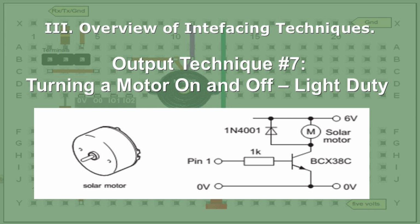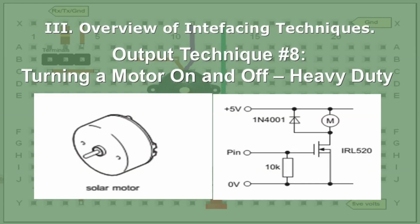And the circuit, you notice, still has the bipolar transistor. It's got a 1K dropping resistor. Turn pin 1 on, it turns the motor on, because it turns that transistor on. Same similar technique. And there's, I think, one with a MOSFET transistor. In this case, you've got a 10K resistor going to ground there. That's a MOSFET transistor.